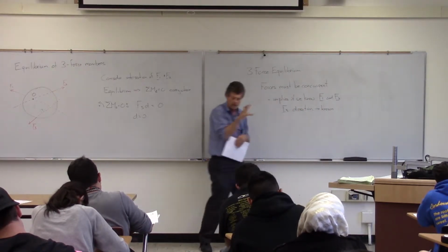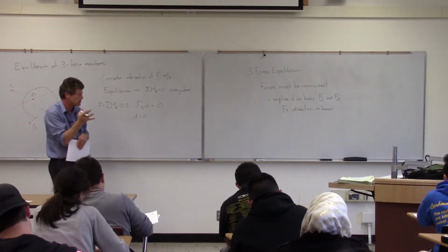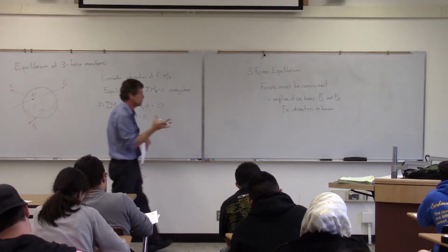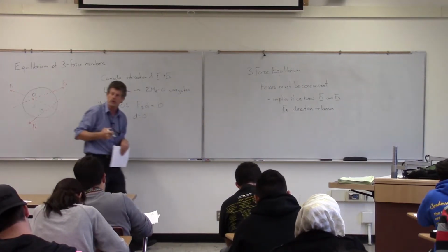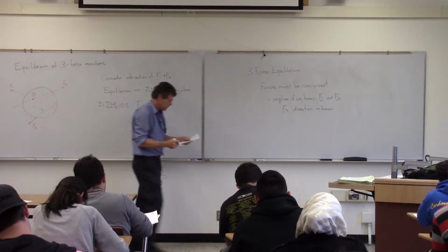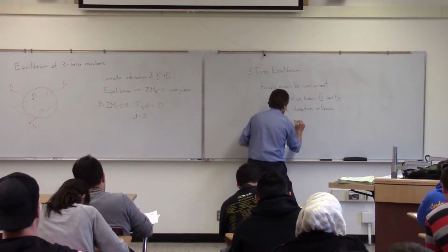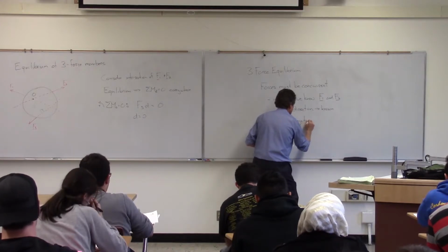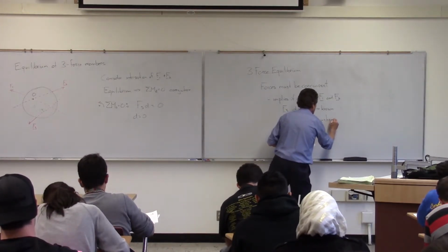So what that says is if I have F1 and F2, I have those values in terms of a vector. So that means I know their direction and their magnitude. Then the direction of 3 I can establish because all I've got to do is find that intersection where 1 and 2 go through. The only unknown I don't have is the magnitude.